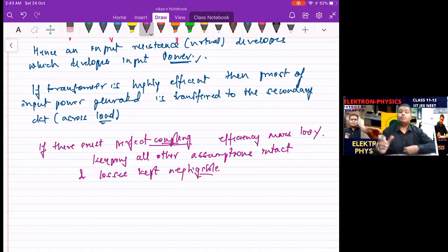Just like we have a input battery, DC battery. So DC has an internal resistance. What will happen? There will be a power loss, definitely. So over here also, if you apply by your side a resistance in the inputs, what is going to happen? There is supposed to be power losses. So 100% efficiency cannot be met. But if you do so, that you try to reduce it by increasing the cost of construction, that is by using the thick copper coils. In that case, the resistance can be minimized to great levels. So even the 99% transformer efficiency will be very good. 97%, 95% is also excellent. Even 90% is too good.